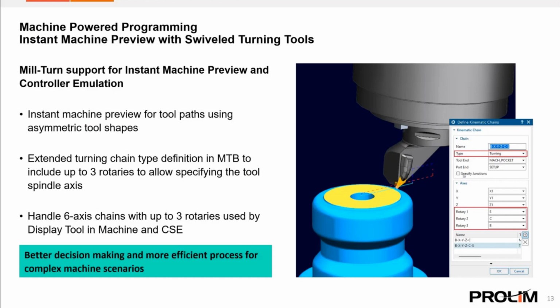So machine code based simulation is already capable of doing the simulation with it, but the logic considering the spindle axis position to swivel the tool in the working plane lies within the simulation driver. So this logic is now generalized, available in NX core, and can be used by all clients such as CSC, DTM, and the post processing, etc.